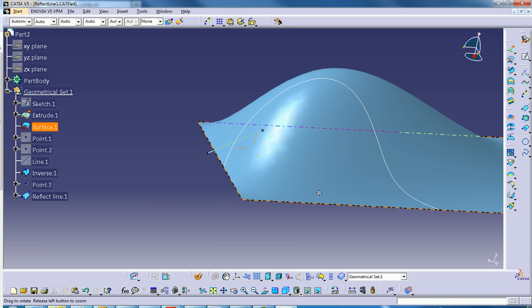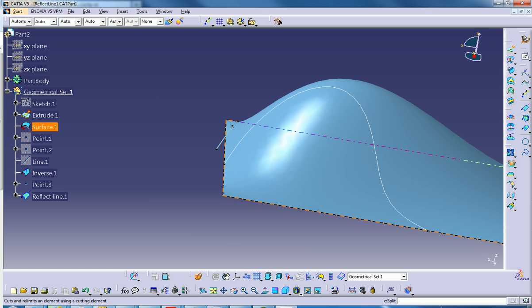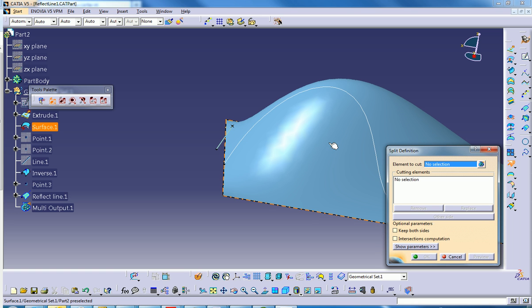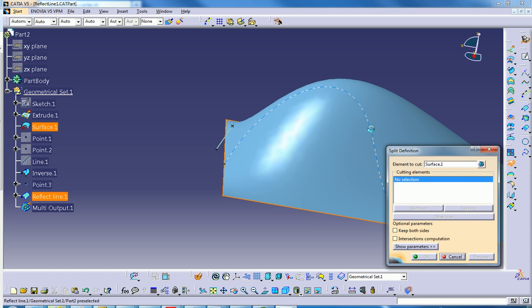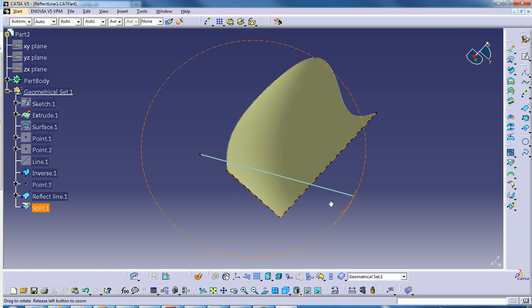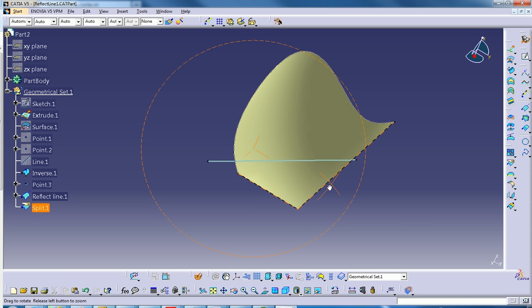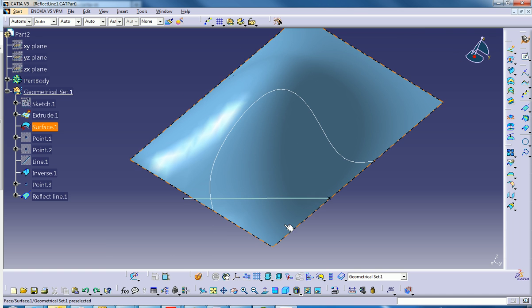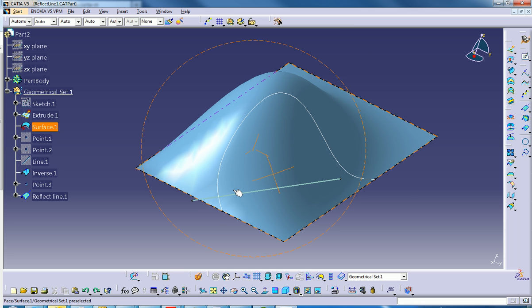We'll discuss more about trimming and modifying surfaces, but I can easily go here, click on split this surface here using this curve, and you can just preview the result, hit OK, and the computer is able to split that and keep only that result here. So this can be one of the applications for using this tool. I would imagine people that use molding a lot would use it because they need to split their objects and create the cores and the cavities. So that can be a tool that can be utilized.